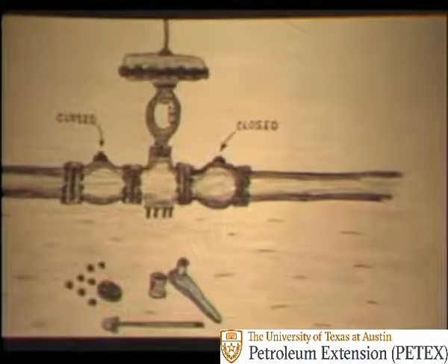Second, if the fluid control dump valve is open but there's no flow through it, it may be plugged with sand or sludge. If it is, open the bypass and close both block valves. Control the liquid level with the bypass valve. Then remove the control valve and clean it out. If after cleaning the valve and returning it to service, the level in the separator remains high, bypass and drain the separator, then clean it out.